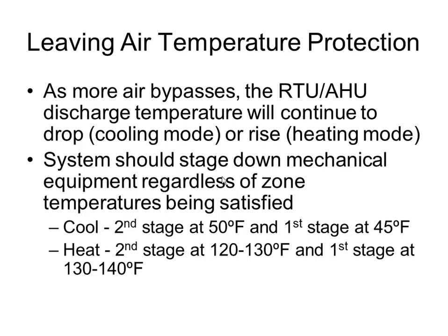So leaving air temperature protection is something that comes standard on Carrier VVT controllers, and it is a safety logic built in for the VVT system. What it does is it reads the leaving air temperature, and as more air bypasses, it actually stages the cooling and heating modes to prevent your supply air temperature from getting too low or too high.